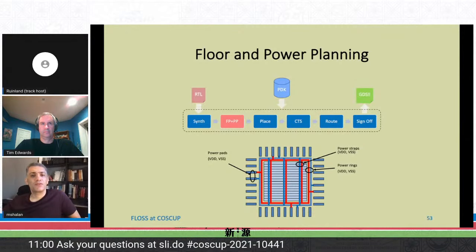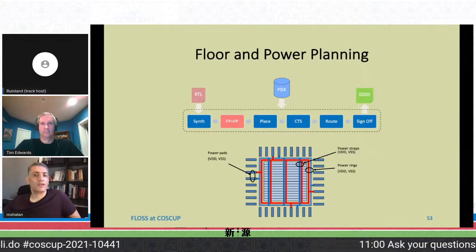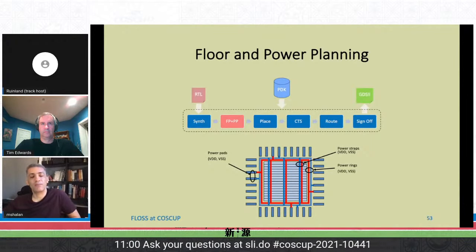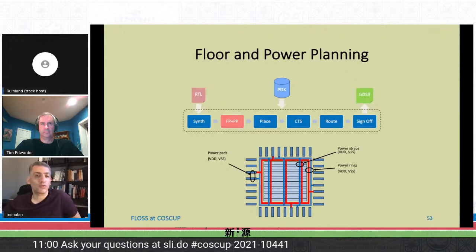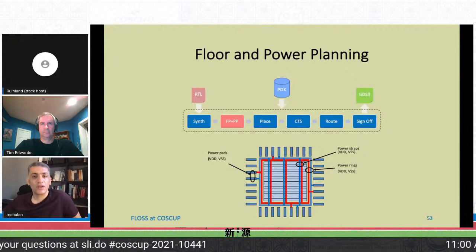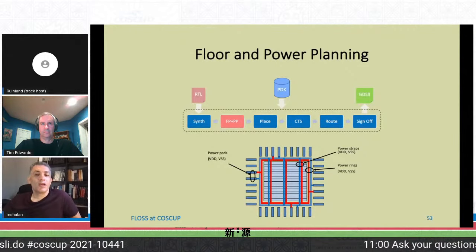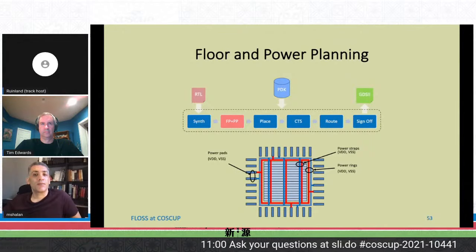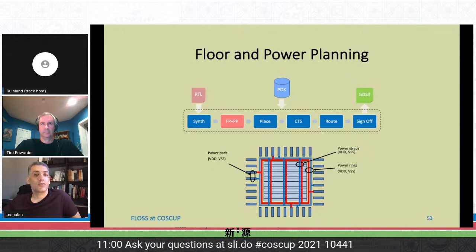This is essential because we need to deliver the supply voltage as it is, so we need to eliminate any voltage drop that could happen on the power distribution network. That's why we reduce the resistance. Also, we make them wide and thick enough to address problems such as electromigration, when we have high currents demanded by the cells during operation.